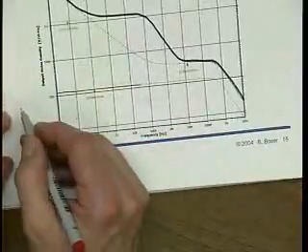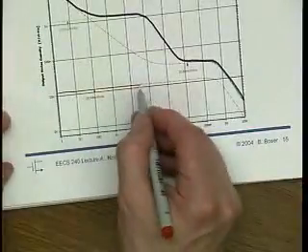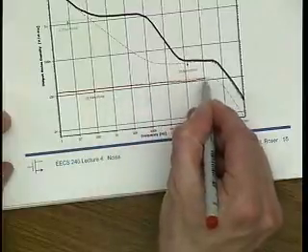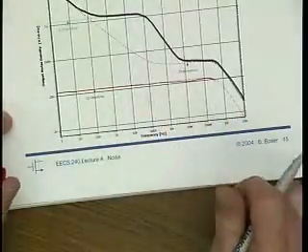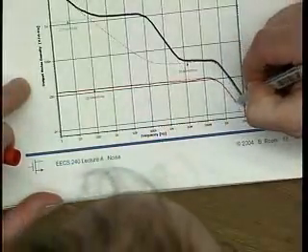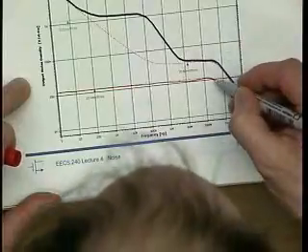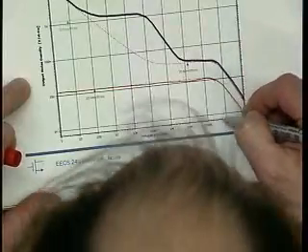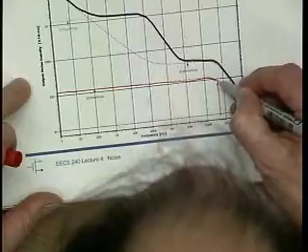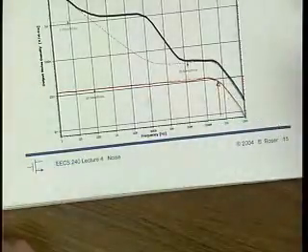So that, of course, is 4kT RL just at low frequency, and then at high frequency, FP2, it should start rolling off. FP2 was 600 megahertz, and 600 megahertz is here. Okay, so that seems to be a winner.